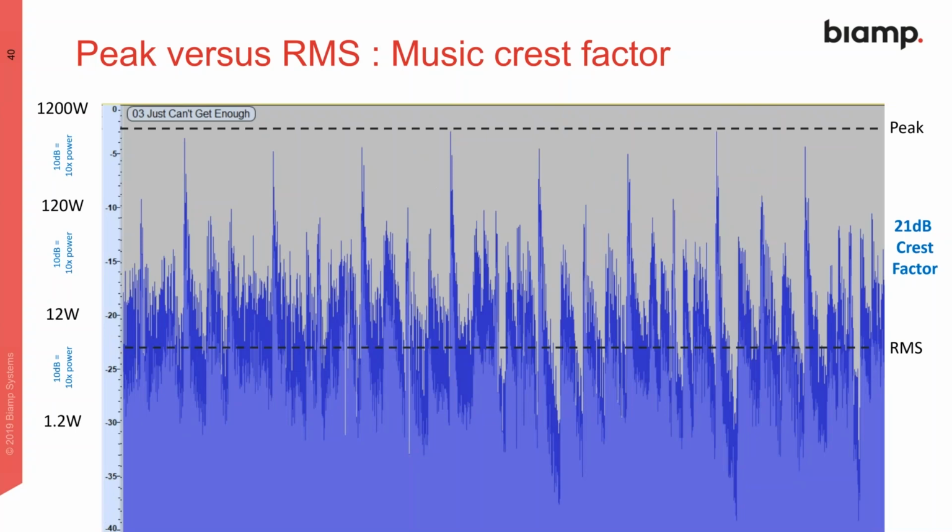So this is a Depeche Mode song, and they're not cresting as high. The peaks are coming in at -3 instead of at 0. So already it's 3 dB lower on the peaks. We're also 8 dB lower on the RMS value. So this song is going to be 8 dB quieter than the other song, and that's just the mix.